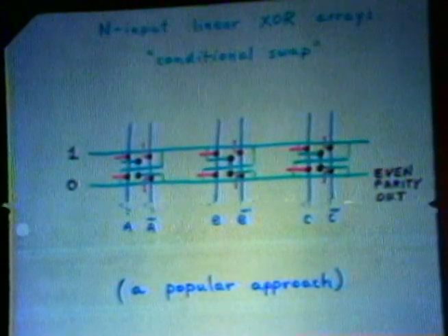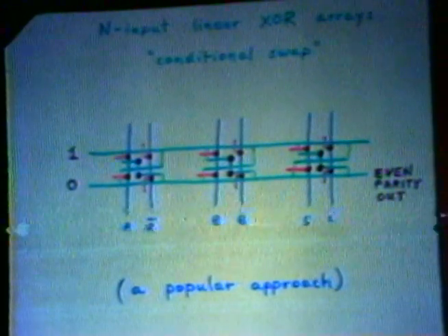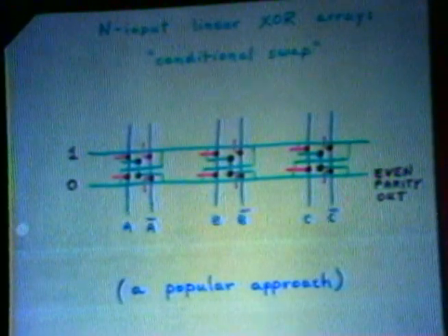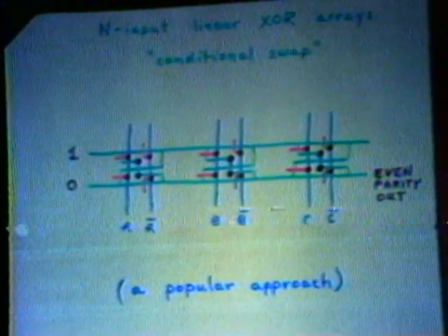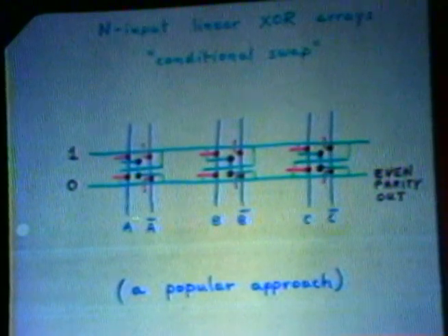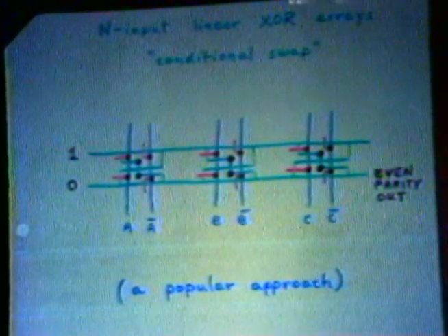This is also the form that was implemented on a chip that was mentioned yesterday, that Hamming code error correction chip, which does like 6 and 7 input exclusive OR functions. And another solution to that is a solution that doesn't depend at all on the fact that what you're implementing is an exclusive OR function, because it's implemented with a 4-input multiplexer.